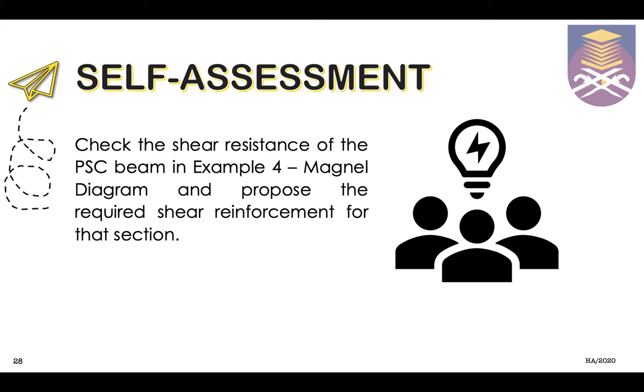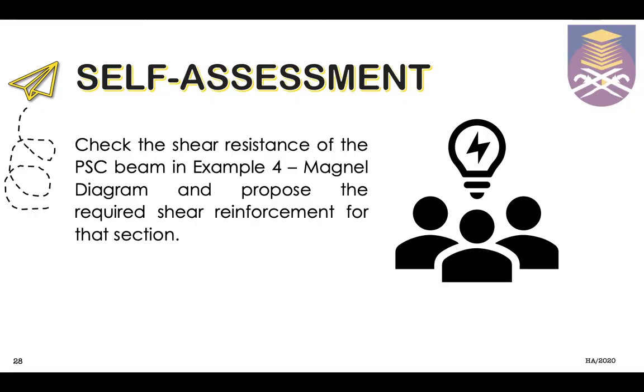Basically what I want you to try today is to check the shear resistance first. No need to propose the reinforcement yet. Just check the resistance, meaning we compare the value of VED with VRDC first, and see whether the shear reinforcement is required or not.